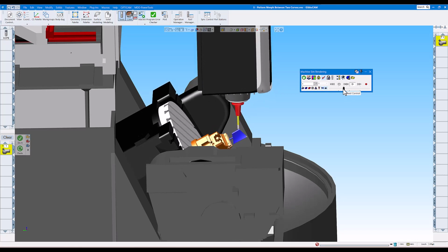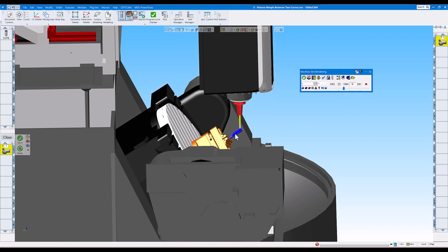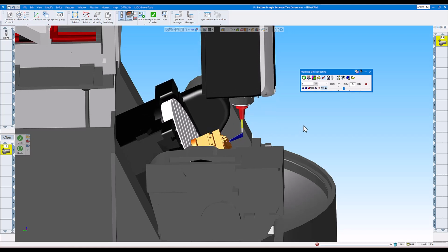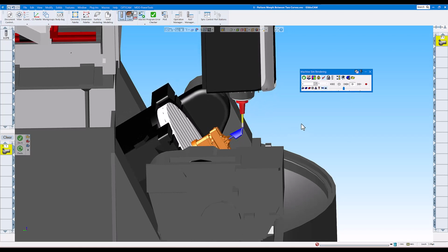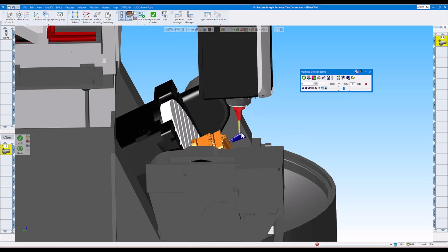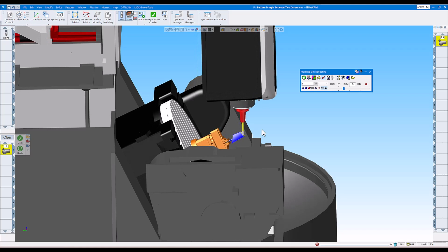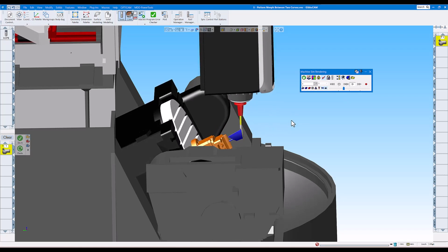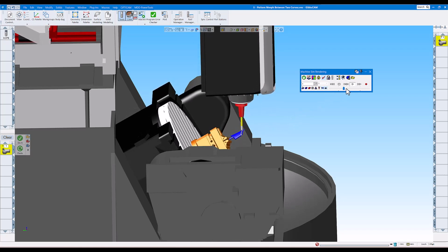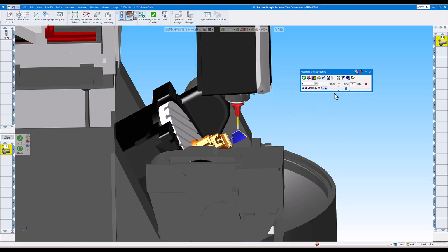And of course, if you prefer, you could go from the bottom up, especially if you're roughing. That might bring the material a little bit farther on the ball end mill up on the side here instead of pushing it. But of course that's totally up to you how you'd like to do that.